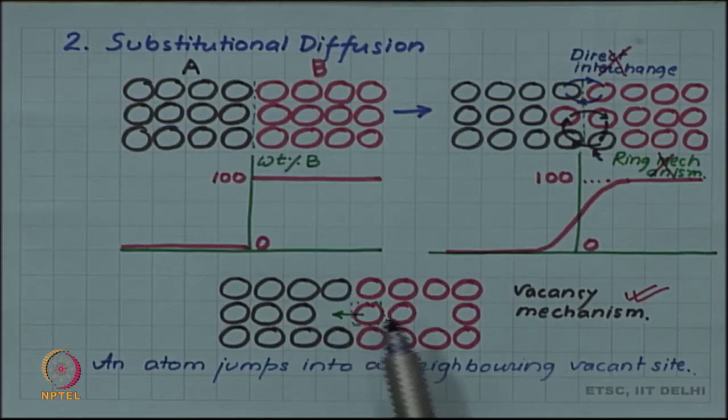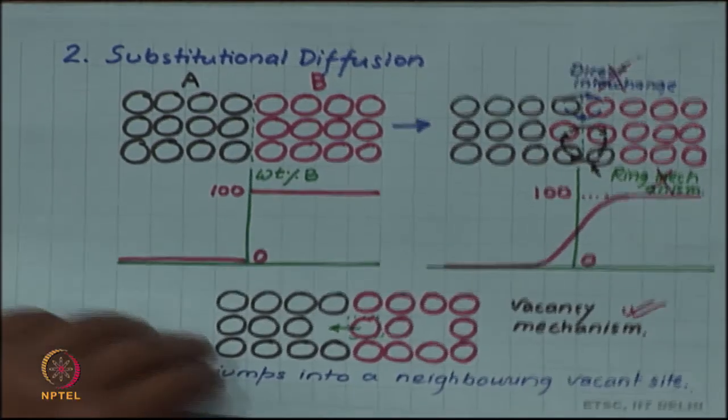You should remember that we have discussed that, and we derived an expression for vacancy, and we found that the vacancy concentration can be anywhere like 10 to the power minus 10. So, only one site in 10 to the power 10 sites is vacant. So, since the presence of vacancy is very rare, it will be a very low probability for an atom to find a nearby vacant site. So, this leads to the general relationship.